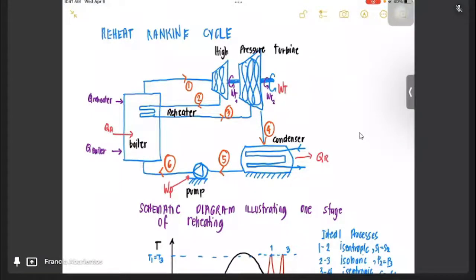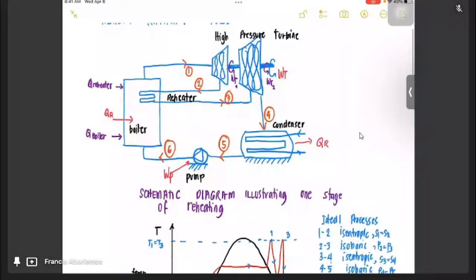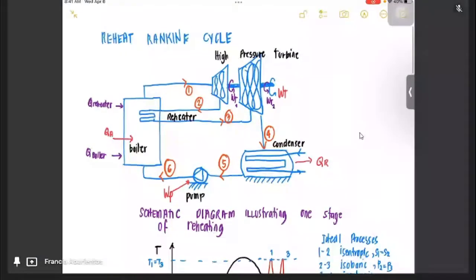So from that, the steam is reheated again. After that, we'll pass through again a steam turbine wherein the turbine blades are moved, or the shaft of the turbine produces a work. So another work. So the total work now is the work from the first turbine and the second turbine.